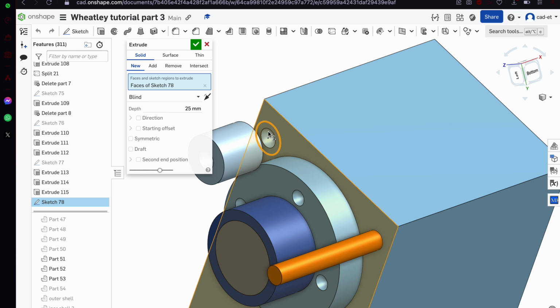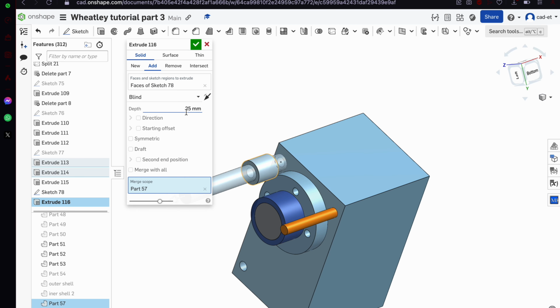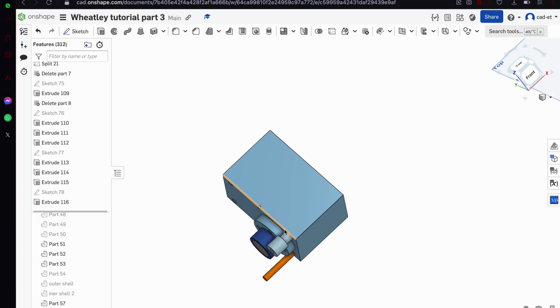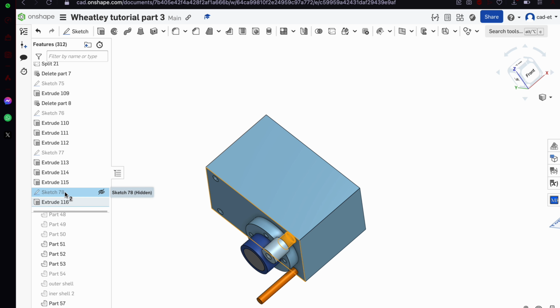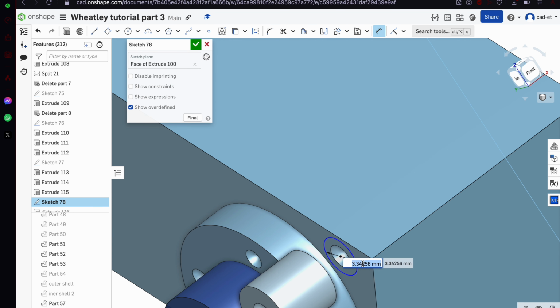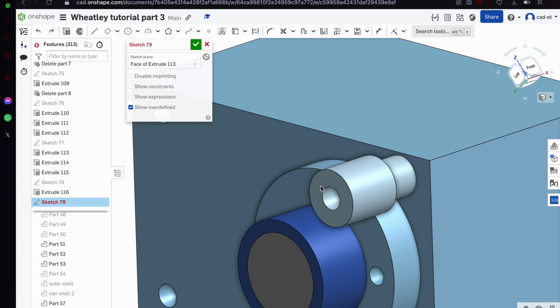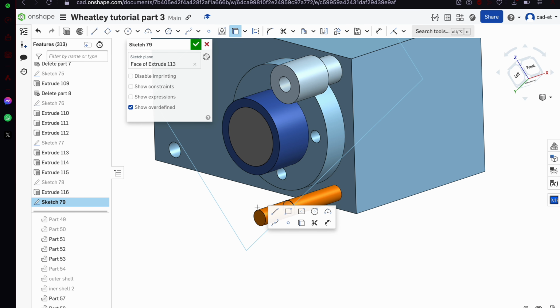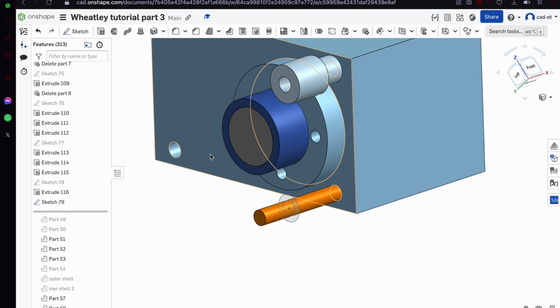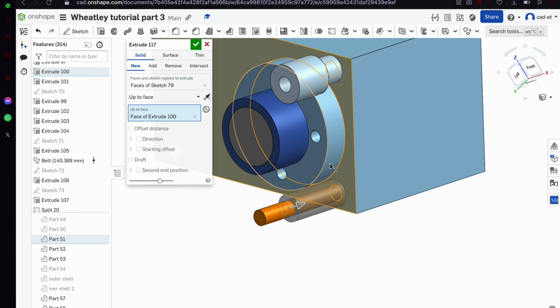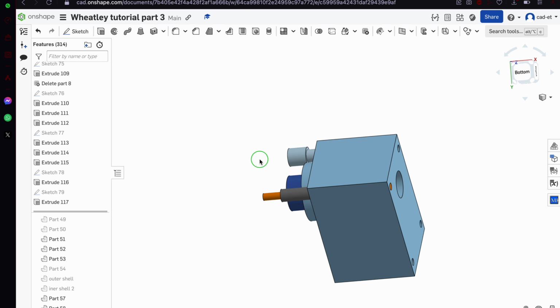Now, I could do away with the motor mount completely on this side and just have it attached by 3 bolts, but I really wanted all 4 bolts, especially as where that pulley is going to be is the bolt that would experience the most tension and compression. So I've had to make this two-stage bearing. This allows the belt to go around it without interfering with the motor, and should prevent the belt from wearing out.